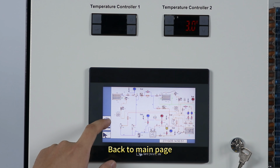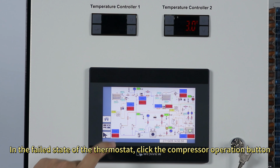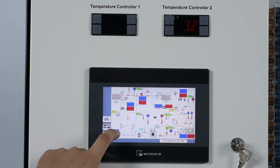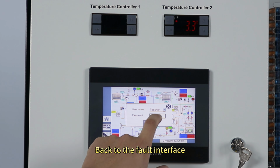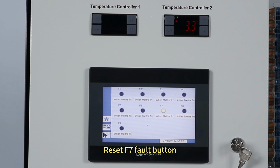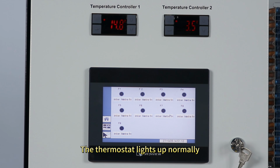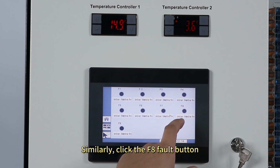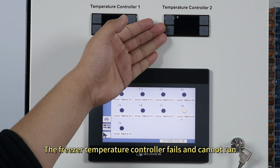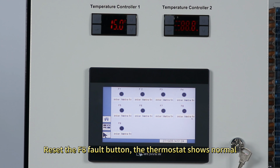Back to the main page. In the failed state of the thermostat, click the compressor operation button. The compressor cannot run. Back to the fault interface. Reset the F7 fault button. The thermostat lights up normally. Similarly, click the F8 fault button. The freezer temperature controller fails and cannot run. Reset the F8 fault button, and the thermostat shows normal.